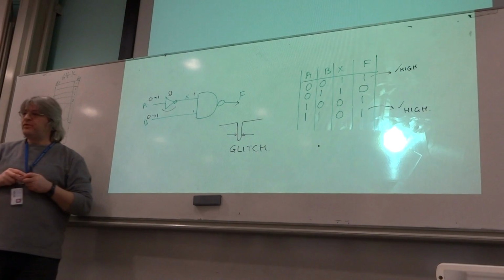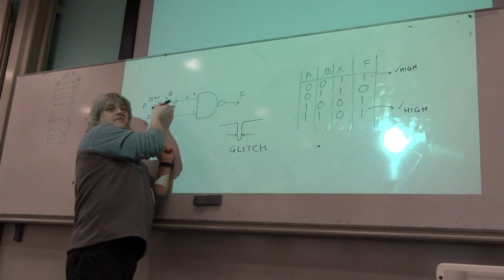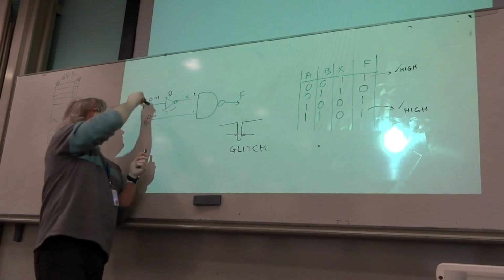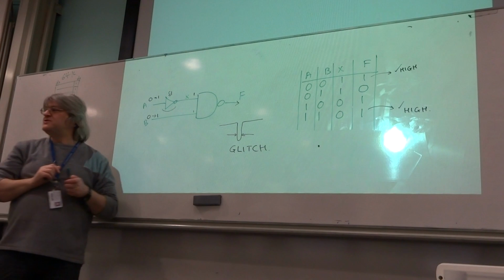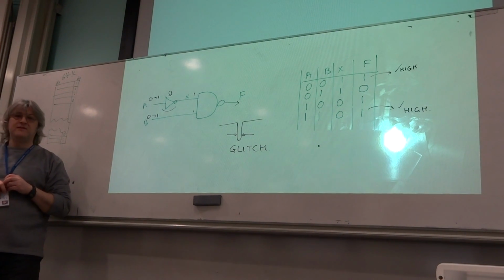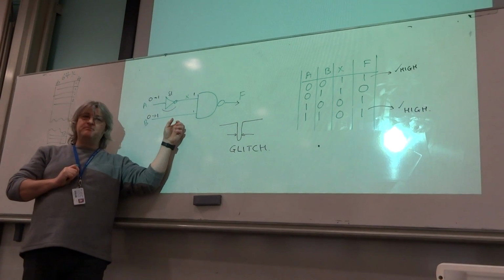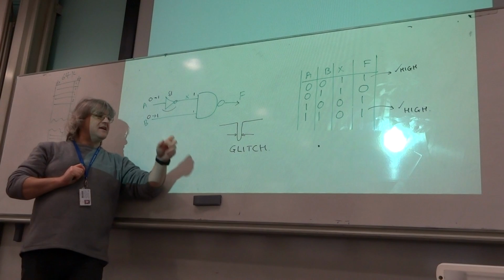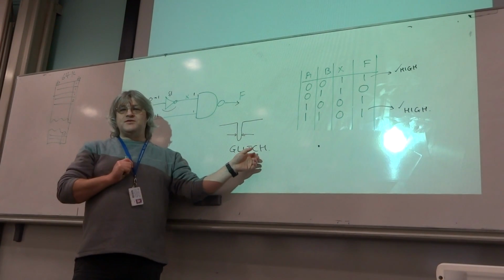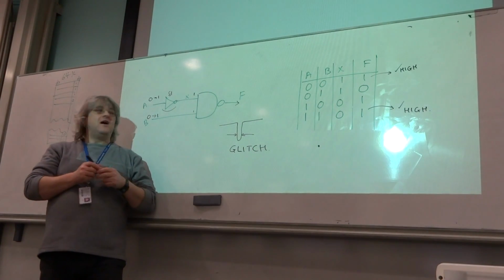And it's a well-known problem with address decoding circuits, where the length of the different paths feeding into the address decoding logic is not the same. So you'd be expected to know in this course about this problem, and that it can give rise to glitches.